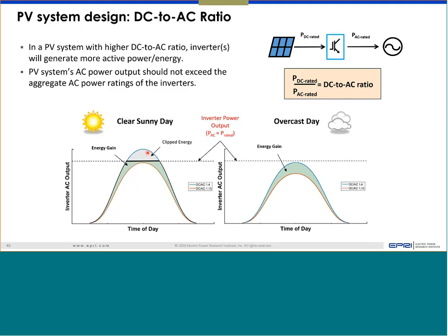The DC-DC converter used in front of the PV panels, if that's large enough, then you can entirely transfer the DC generation from the PV into two directions. One goes to the inverter, another part goes to the battery. Yeah, that's possible, to capture the clipped energy. And some of these vendors will identify that as one of the benefits of having a hybrid system and having a larger DC-DC converter. I hope I answered your question, but let me know.